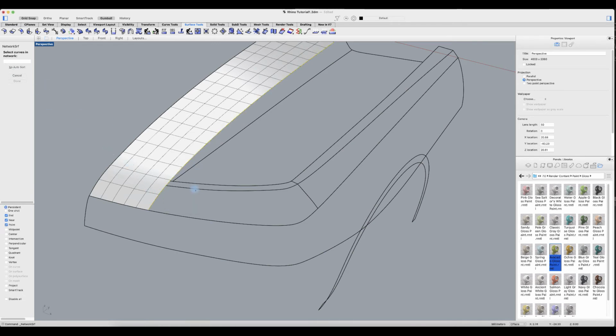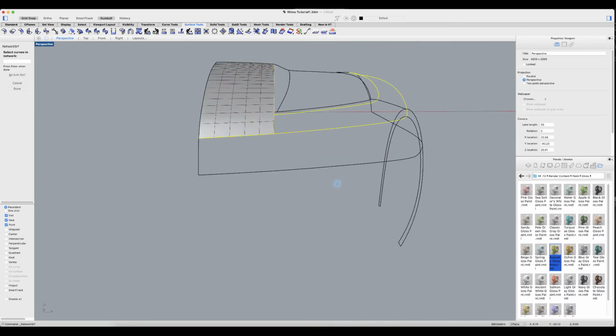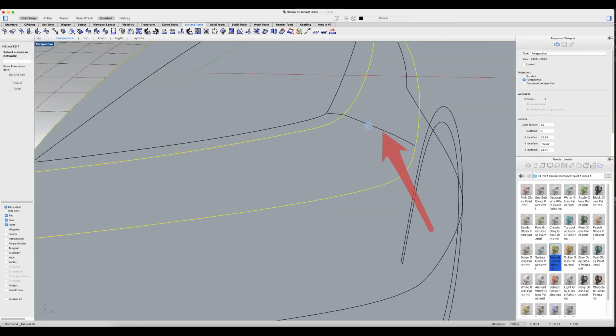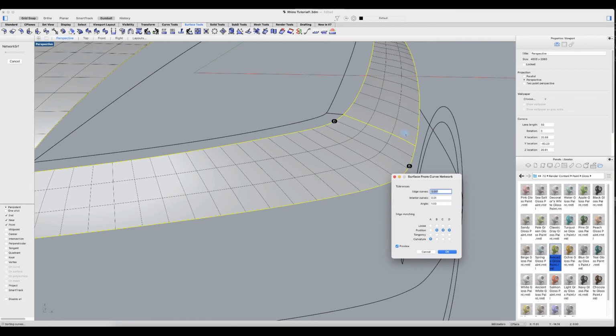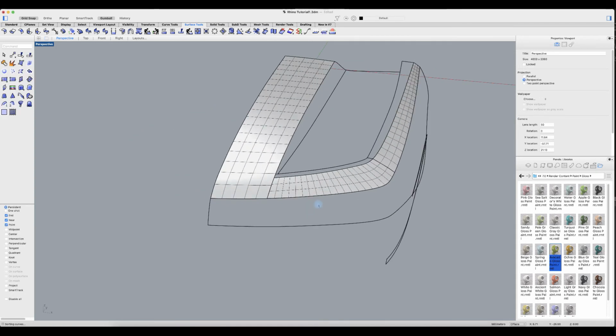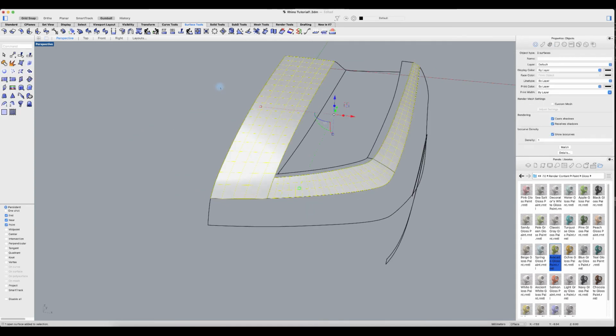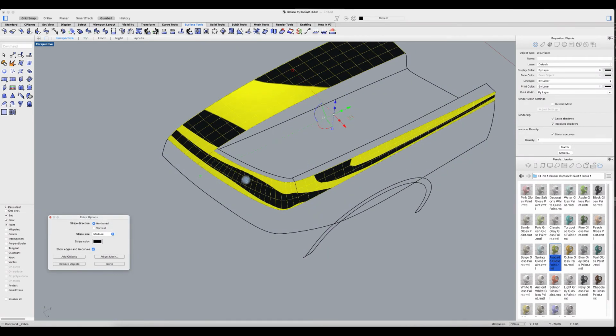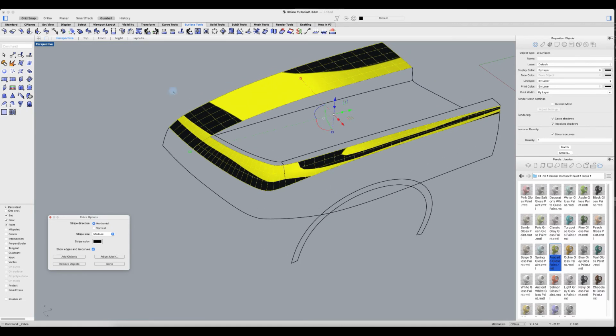Right there, I'm going to do that edge, get that line, come down here, and I am going to work with this constraint and see what that does for me. And so you can see it distributes all of those pretty nicely. And on A that would be a position tangency, but I'm going to push that to making sure that we got curvature. So this is one continuous surface. So definitely you could see it took us just a few seconds to create a much refined continuous surface.